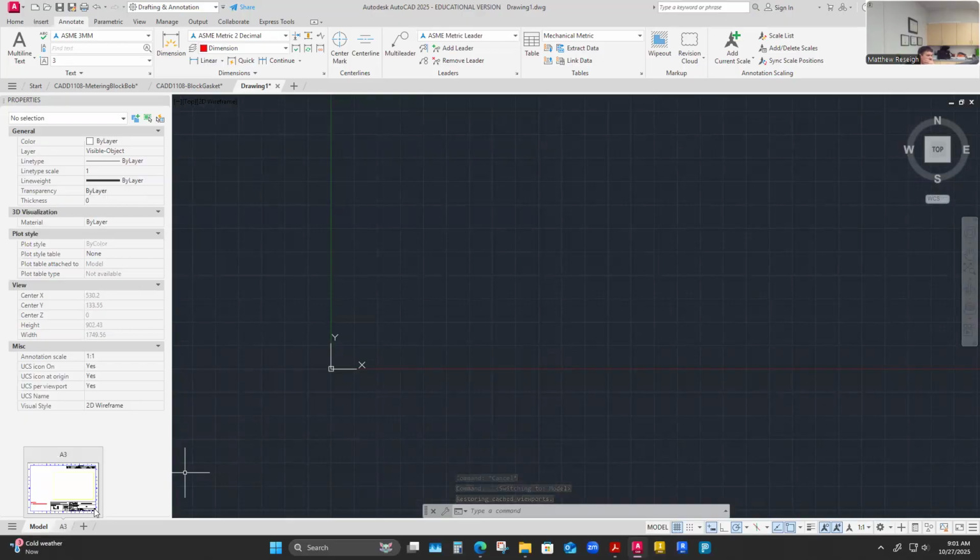I mean, it's not wrong to have built the table here. It's just that maybe I would build it through the viewport if I did that. It's text, and so maybe I want it to be annotative. So if I did build it here, I'd do it through the viewport because my little red flag in my brain should go off: hey, I'm adding text to my document. Do I want to be at the model scale or do I want to be at the paper scale?